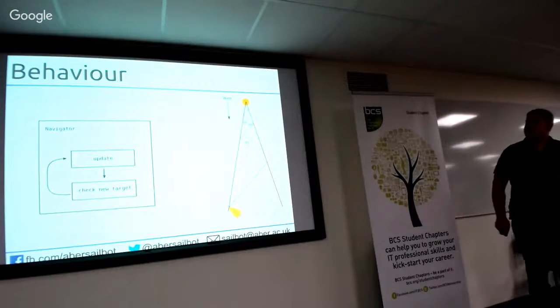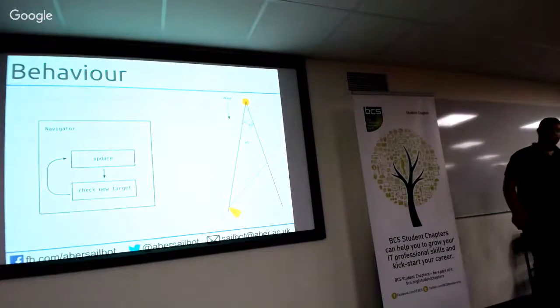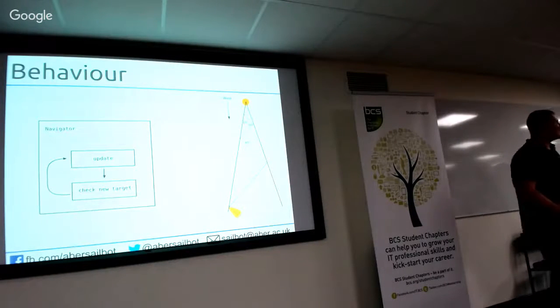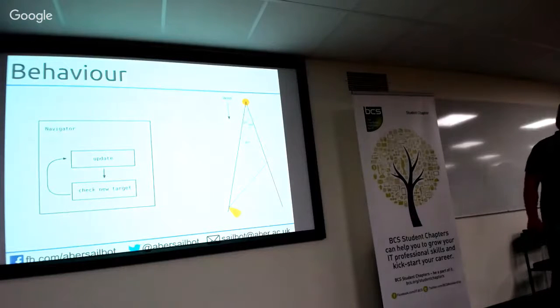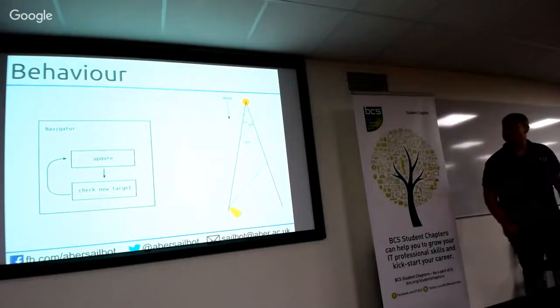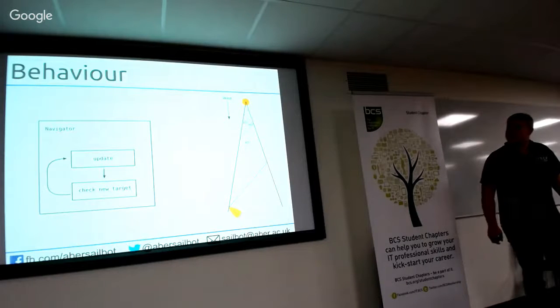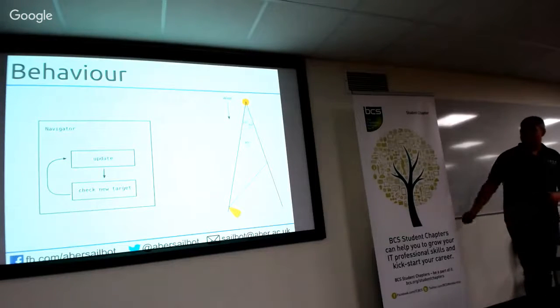As far as behavior, this year we were working on how we were going to go upwind. If anybody doesn't sail, you can't sail into the wind. So you've got to go as close as you can without going directly up, which means a zigzag. We set a 15-degree angle between directly upwind and the edge, as you can see on the triangle. We were measuring the angles, and once we got beyond 15, we would tack and head in the other direction.